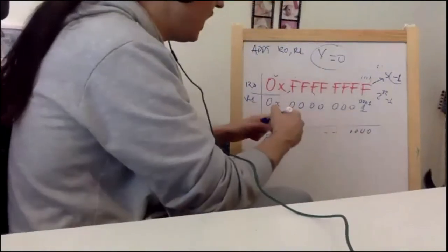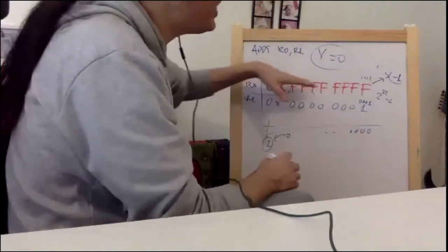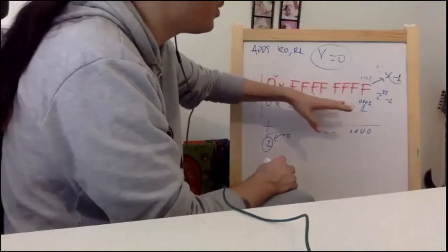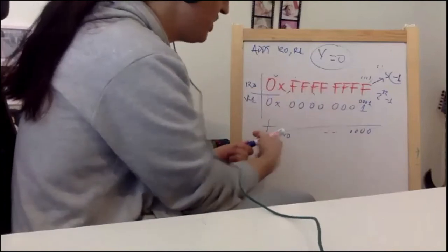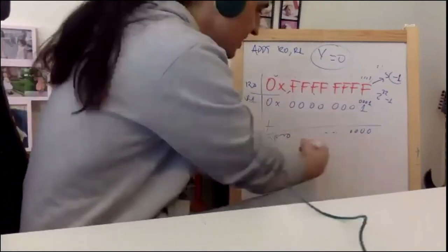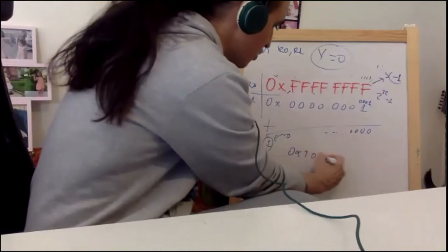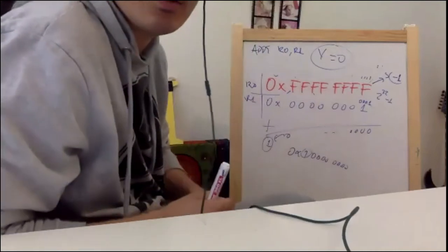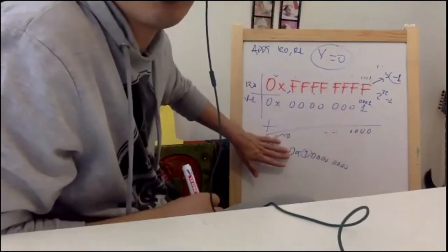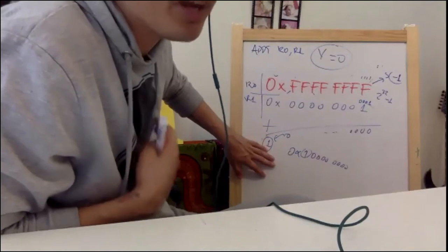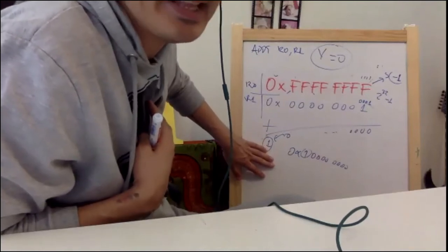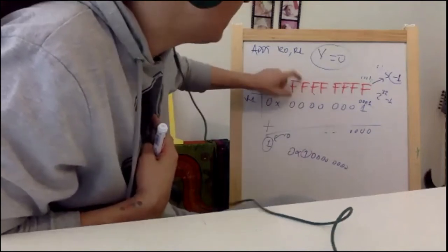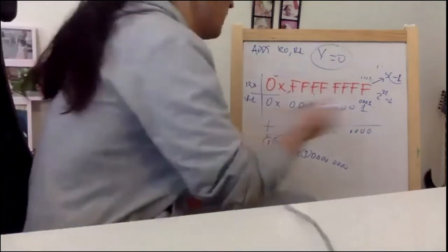Okay. I do this. I'm now assuming that these are unsigned numbers. So this is not the negative bit. I sum them up. I have a number which is all zeros. If I represent it in hexadecimals, this is 1, 0, 0, 0, 0, 0, 0, 0. So I have an extra digit of hexadecimals. I cannot represent this because in my system it's 32 bits. I can only represent 8 nibbles, not 9 nibbles. So if they are unsigned, the result cannot be represented. That's why the carry is 1.